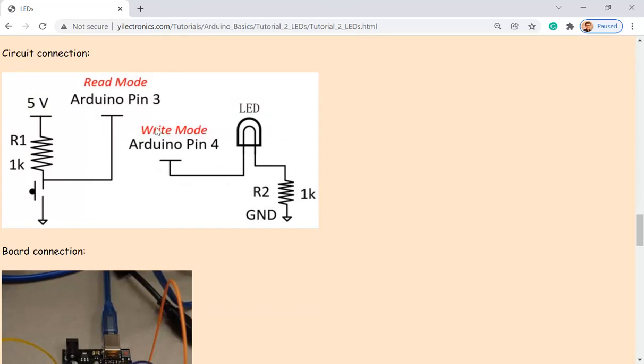So I have a little control using the Arduino. So these are 2 separate circuits. This push button is going to send a 0 signal to one of the pins of the Arduino, like pin 3, and you have to write an Arduino code to sense that. It's like an if statement, right? If this one becomes 0, then I'm going to turn on this LED, which is controlled by the other pin. You know what I mean? It's not directly controlled by the push button. You have to write a little Arduino code to control it. Get it?